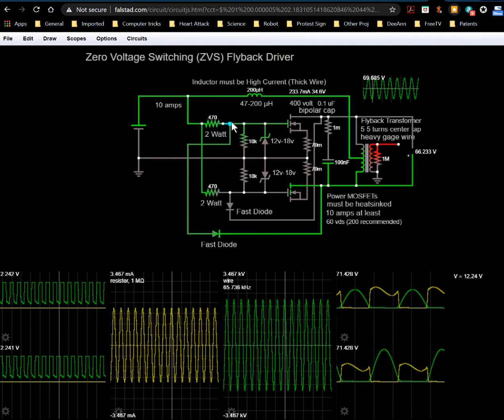So that means this transistor is on because it's got 12 volts across it, which is a good operating voltage for this FET, whereas 2 volts is a bad operating voltage for this FET. So it's effectively off, meaning the voltage across it is high because its resistance is high at that point.